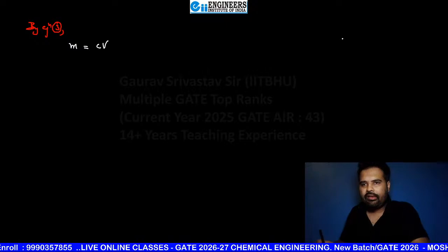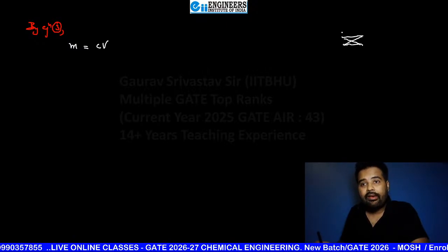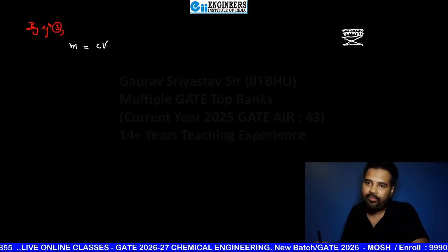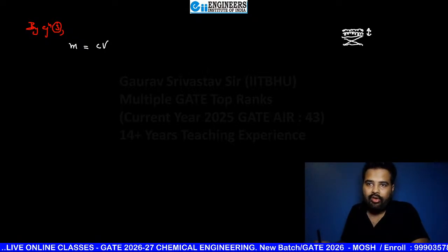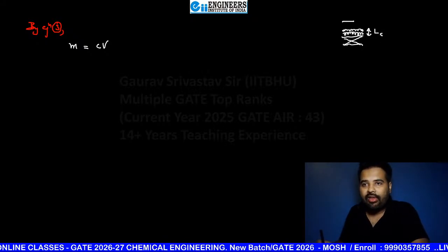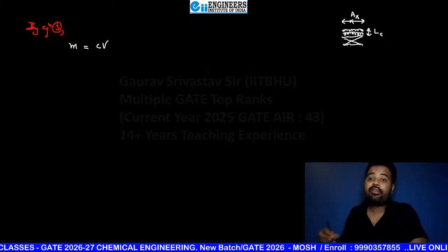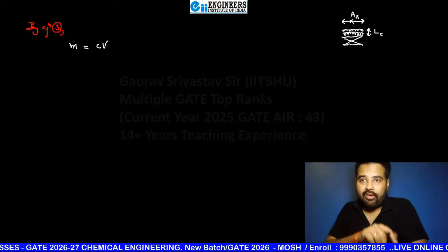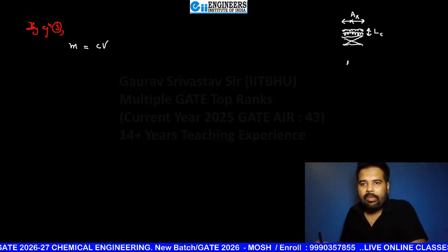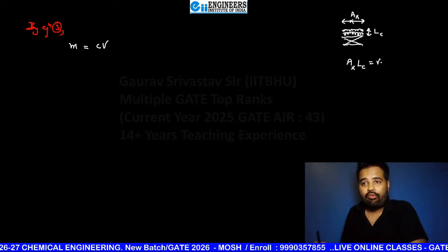See, this is your filter media, and this is your cake above this filter media. We are focusing on this LC only here. If the cross section area is AX, this is area, this is not length, and we multiply this AX with this LC, it will be the total volume of cake.